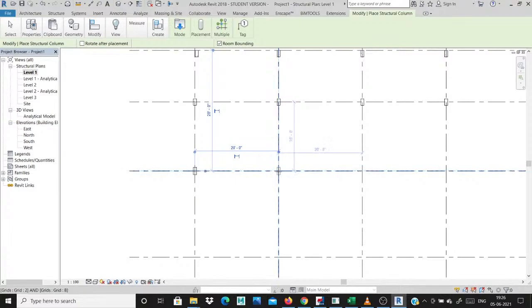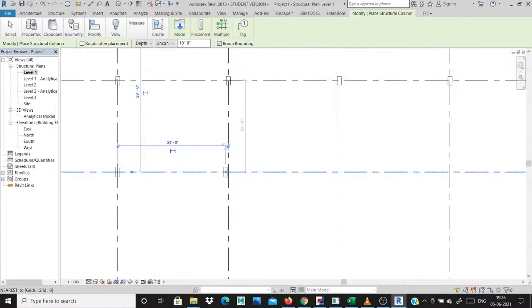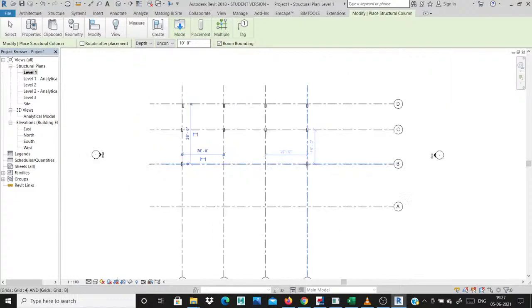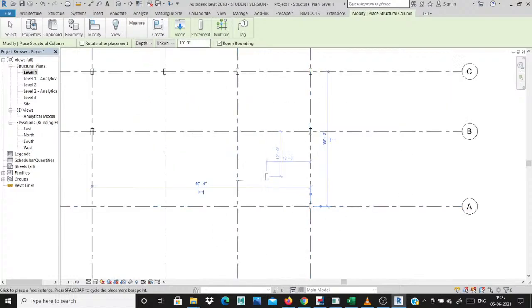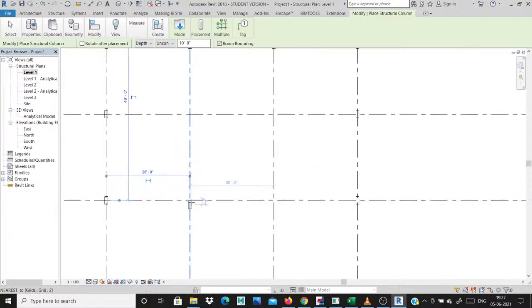How to give the orientation for your buildings? See, this is our orientation. I need this type of horizontal orientation. I simply put these columns. I need the center 4 columns with depth orientation on the Z side.